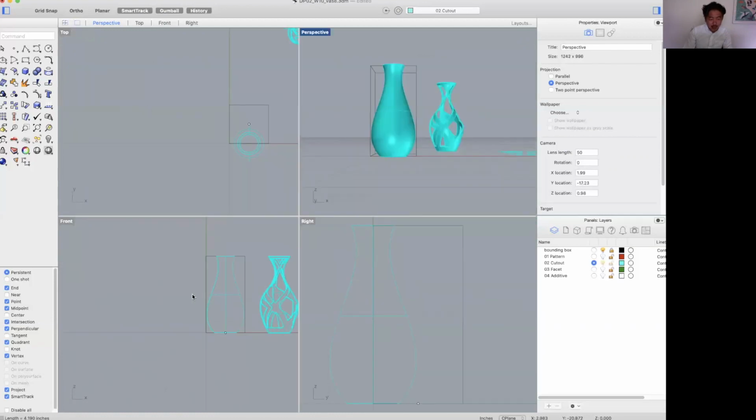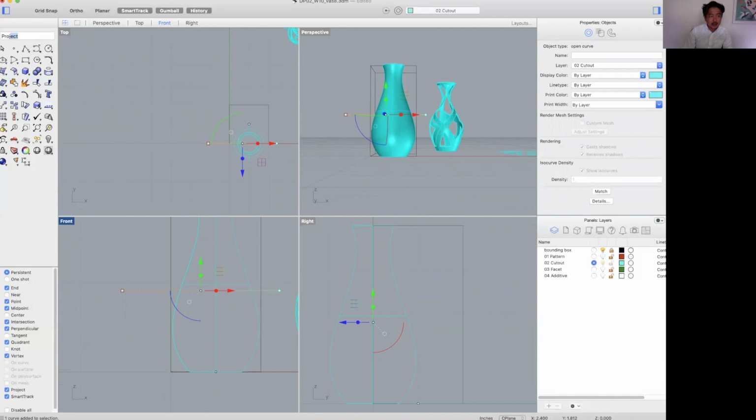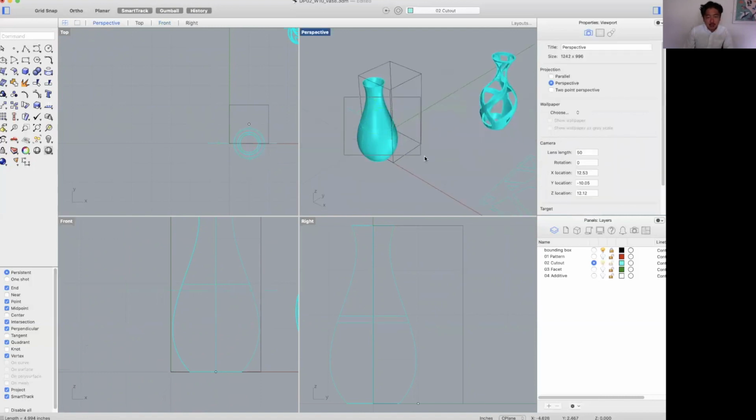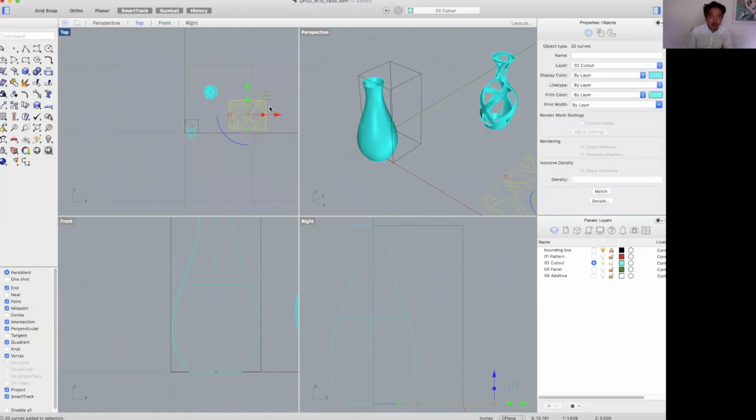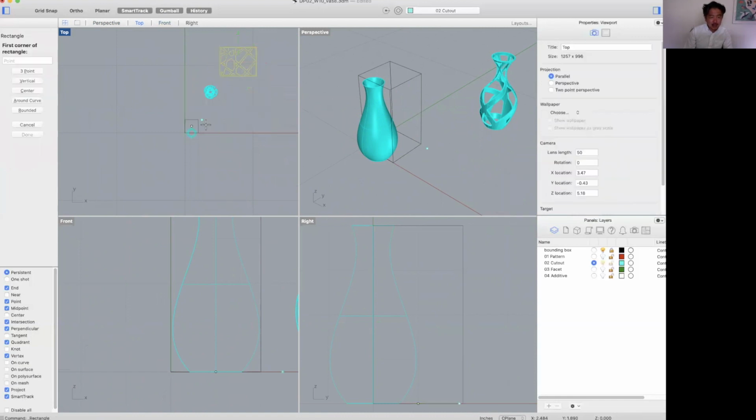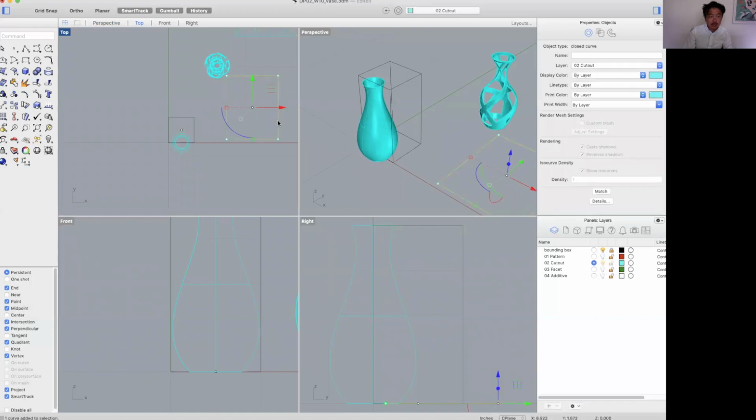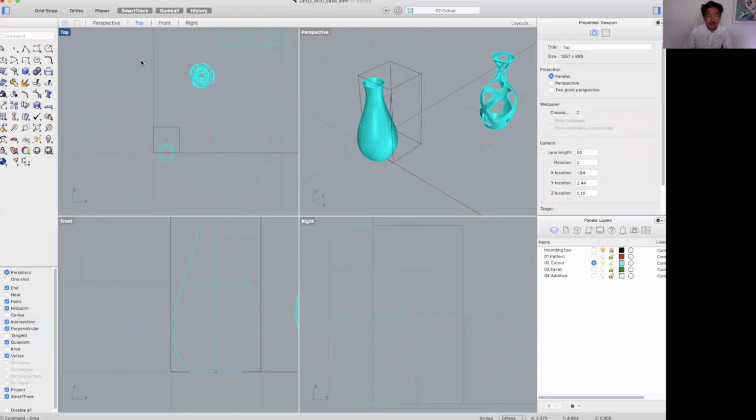For the circumference of the middle part, I would like to just project this line onto this surface and then get the length. So the length of it is about 4.9. So the proportion of my pattern on the flat is about 4 by 5. So I'm just going to draw a 4 inch by 5 inch flat drawing here.